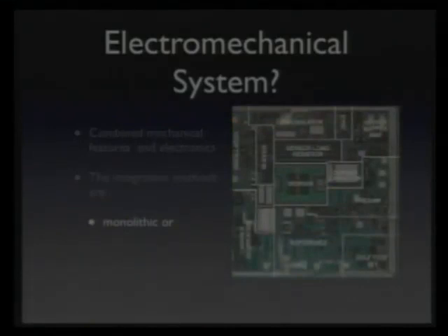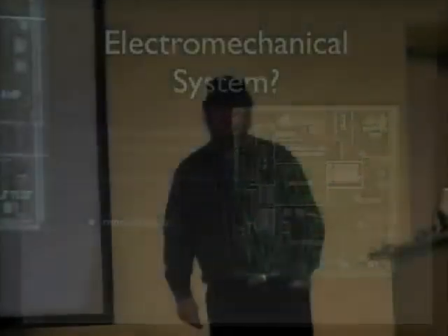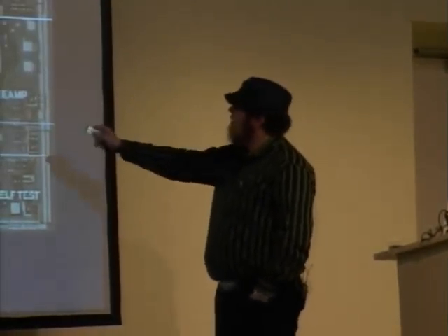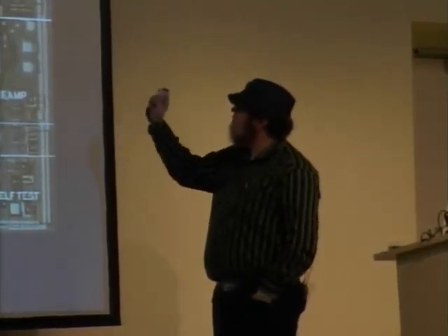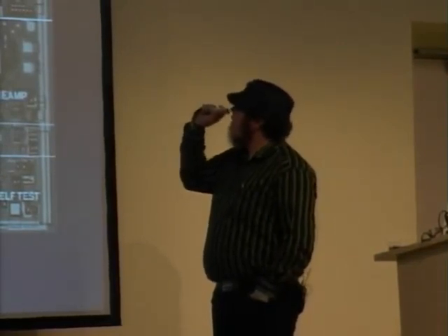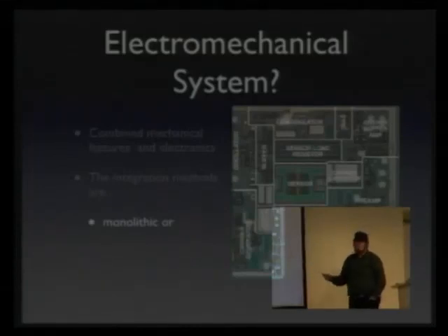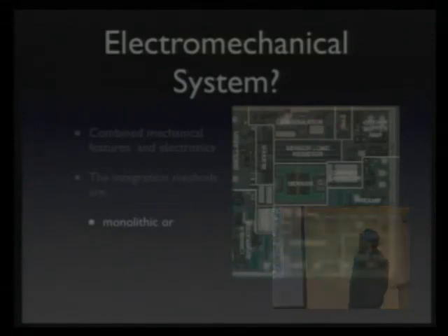But when you want to have a real system, you have to integrate it with electronics, because you want to have a standardized interface. You probably even want to have already a file format, which is nice to have and easier than to implement afterwards. What you see here is a standard accelerometer from Analog Devices. Exactly, it's an ADXL202, so it measures in the range of 2G in one direction.